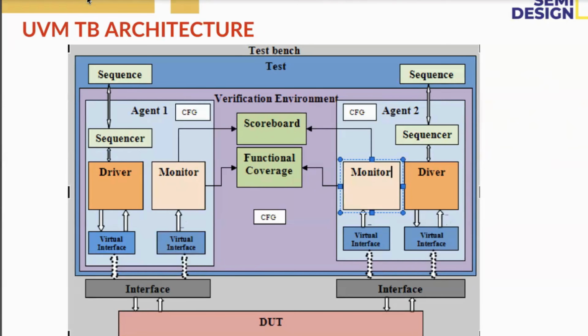TLM is nothing but transaction level modeling. Okay, so here if you see from the sequencer to the driver, we are using one TLM port, okay, and monitor to scoreboard. We are not sending only monitor to the scoreboard. We are sending to two different blocks: monitor to scoreboard, monitor to functional coverage. Okay, that means 1 to 2 different blocks.